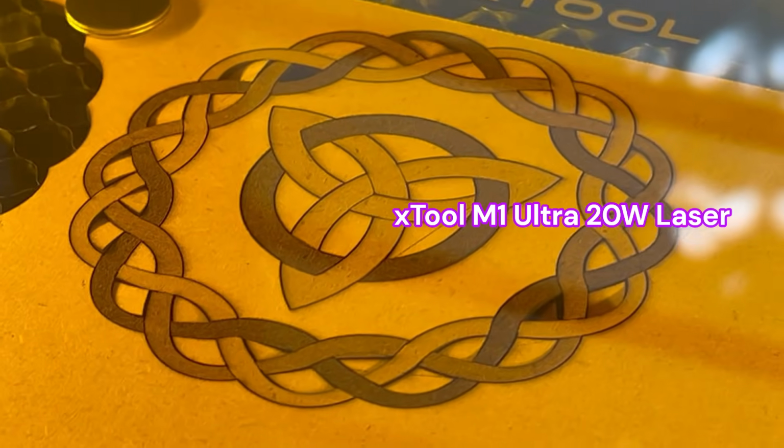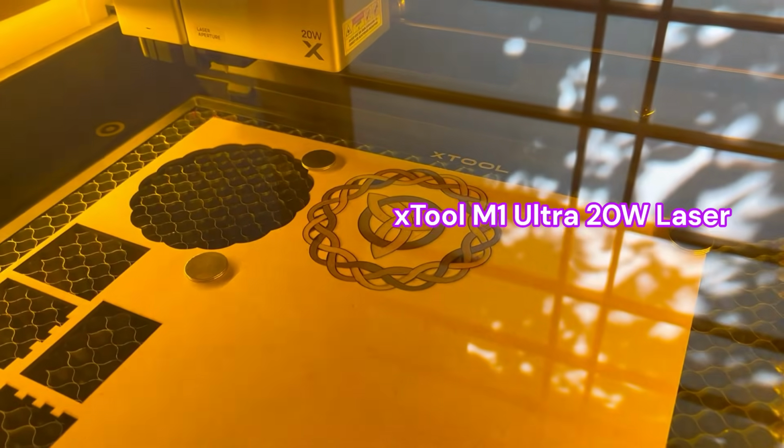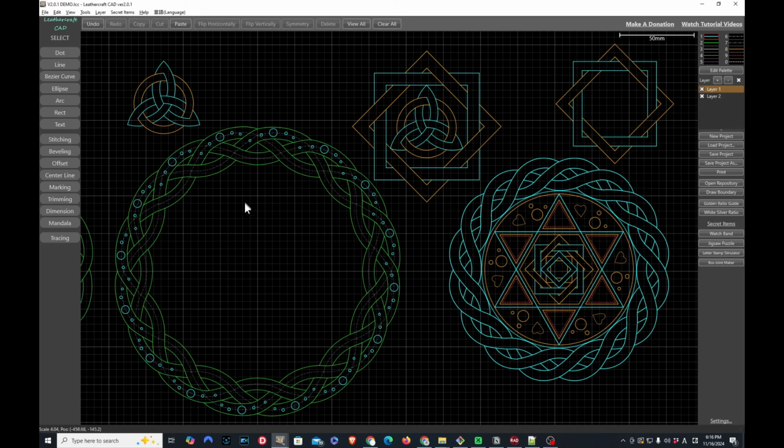But sometimes xTool's XCS software and other software doesn't like the way it was grouped, and sometimes it created a weird line between shapes. So I did some research and changed the algorithm of the SVG export, the order of grouping, and the intersection identification, so that it will be imported as I want it.